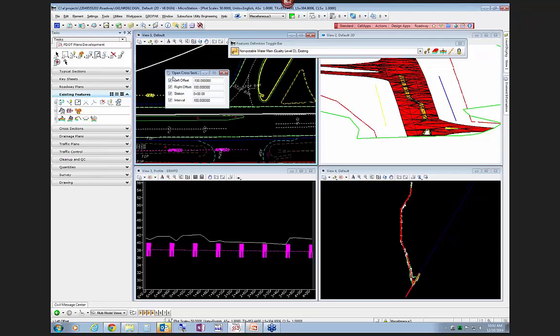If you do not check this field here, station, it will crash on you. I'm just telling you that up front. We found this out in training, that as long as you make sure this box station is checked, and then you can go ahead and eyeball the left and right if you want in the interval, but as long as this station is checked on this baseline in your topo file, it won't crash.